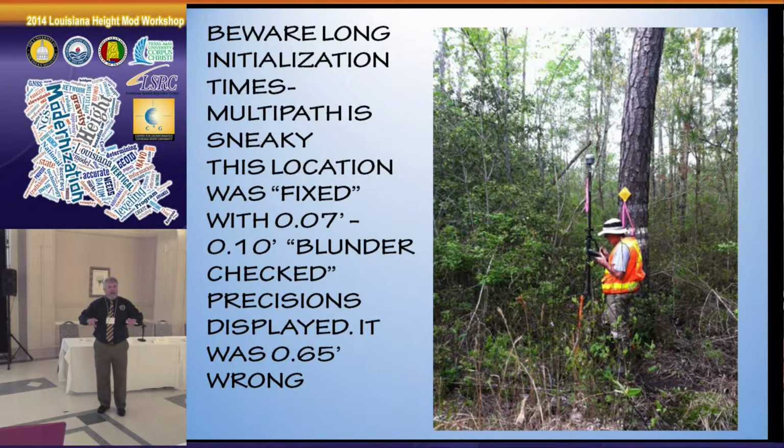Here's the why. It was a long initialization time in the trees. Friends, don't let friends RTK under canopy. I'm sorry. It's still true. It may not be true forever, but as far as I'm concerned, it's still true. Beware long initialization times. If it's sitting there and trying to figure out how many cycles are there from that satellite, and finally says, got it, fixed. Beware, okay?